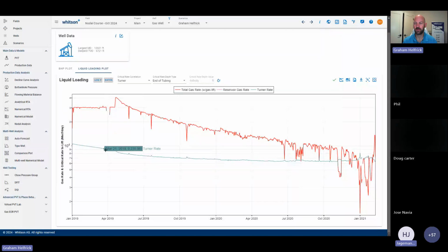The way I used to describe this, I would have a hair dryer and a ping pong ball. You turn it on, and the ping pong ball is just suspended in the hairdryer's wind, right? So we have 2 effects happening. We have gravity trying to pull the ping pong ball down, and then wind causing drag on the surface of the ping pong ball trying to pull it up. When the ping pong ball is just sitting in the same place, you have this equilibrium where those 2 forces are equal, right? It's not going anywhere. And that's what liquid loading is like.